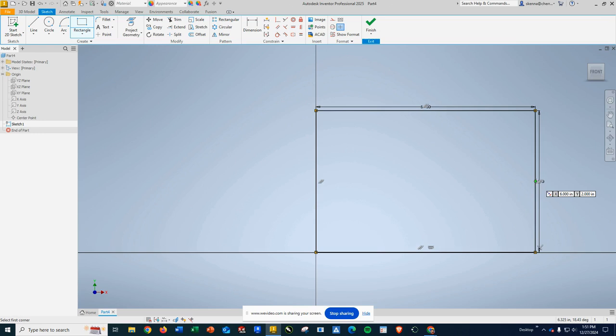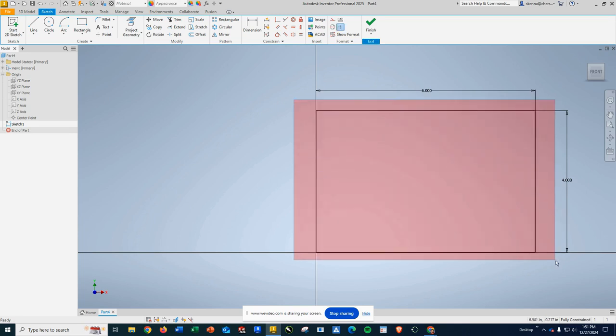So I would just get into the habit of, if it's a length that you know, go ahead and define it as you type it in. The other thing it does, as you can see, is you do maintain the rectangle tool, by the way, until you hit escape, and you can move various things. So I'm going to move these dimensions just out away from the shape a little bit. But if I click it again, or if I highlight all of it again, you can see it added relationships.